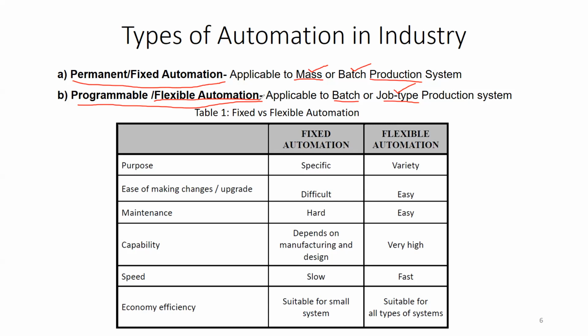So suppose the first 10 machines are used for batch production of the first part. Now for the second part, maybe the first, third, fifth, eighth, 10th, 12th, such type of machines could be used for production of the next part. Okay. So there what you can do is reroute the movement of the unfinished parts within those machine tools.